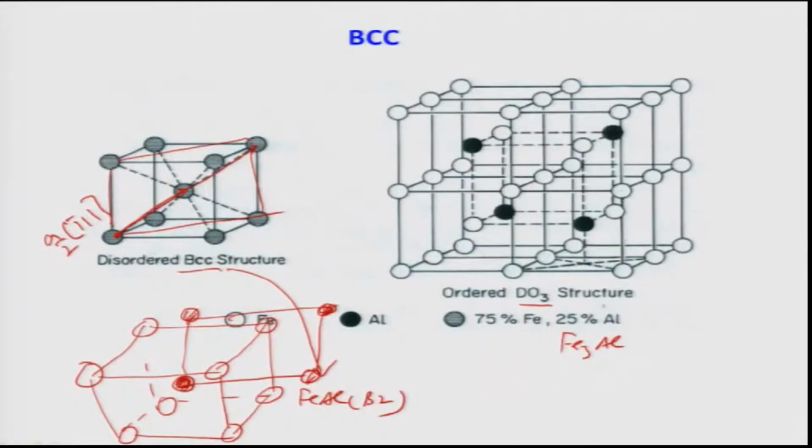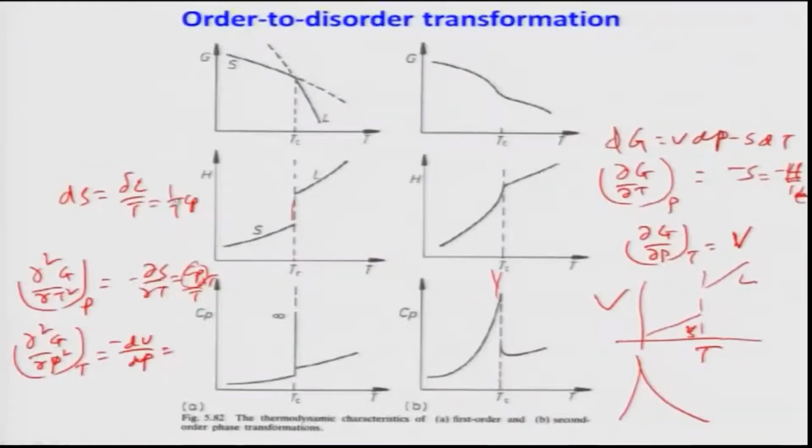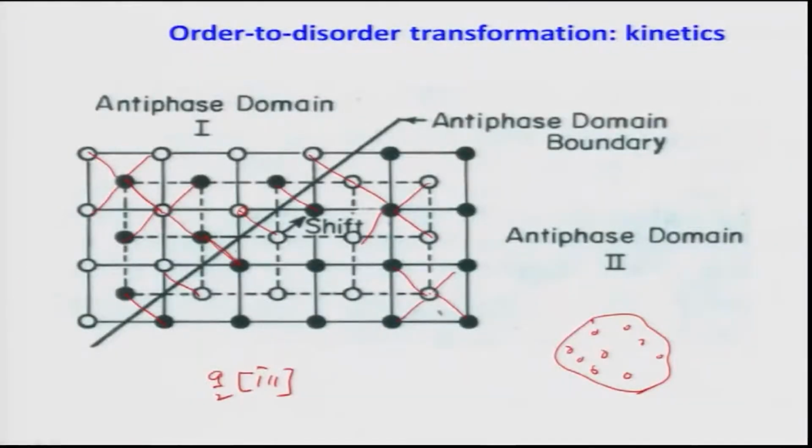That displacement is equivalent to displacing the atoms here, as shown, in that way. Obviously, in a Cu3Au structure it will be 110, not 111. So half <111> along the 111 plane is the displacement vector.